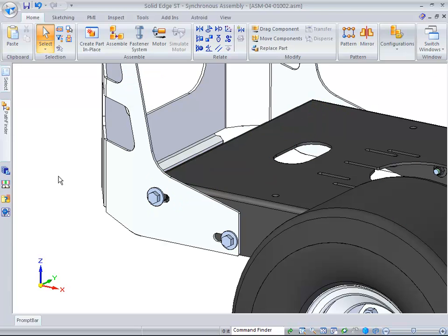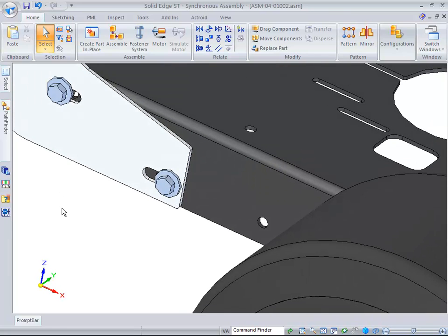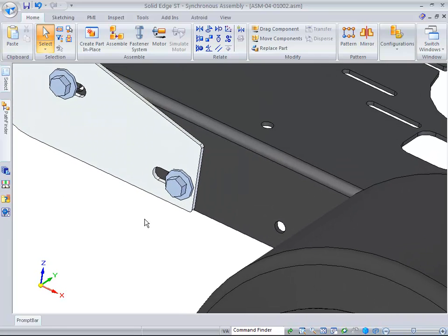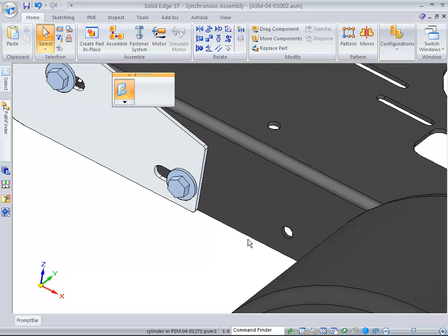Simply double click out in space, because now what we want to do is we want to move this front face and this hole. Now you can come over here and you can select the hole first or the face. It doesn't matter which one you select, but hit the space bar because you want to add this face to it, and then simply grab onto the steering wheel and you're going to move it towards the front of the mower, which is to the right.